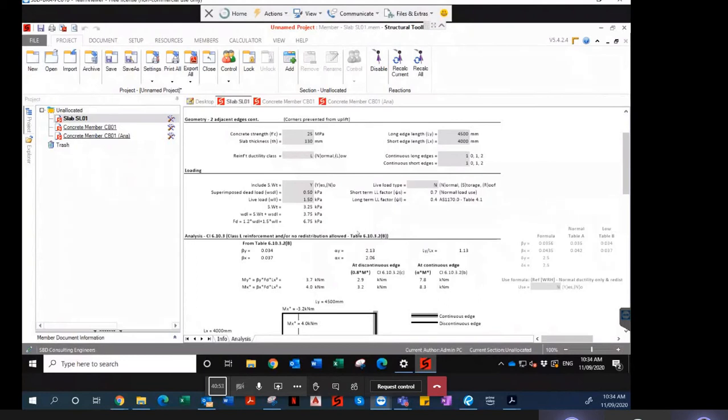Are you guys following me? Yes. So what I'll do is, in my analysis, I'll make that into 0.8, and I'll make my live load as 1.8.